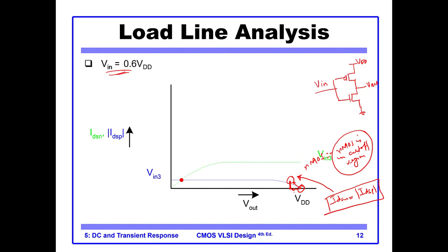Now we increase the voltage further, and you see you are entering the other voltage level, the logic 1 level. This means that we have logic 1 at the input, which means that now this will be off and this will be on. You see now that both the curves cross here, so you have the output voltage which is very close to 0.